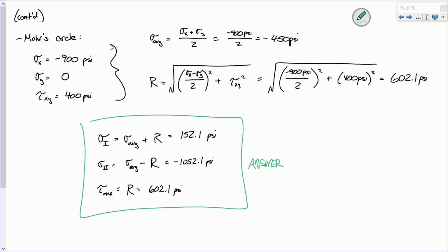By changing your orientation, the stresses get higher, okay? We're looking for worst case scenario as designers, okay? So while our bending stress formulas and shear stress formulas work nice to give us those individual stresses, when you've got multiple stresses going on, everything changes. This shear stress serves to up this at a different orientation. And vice versa. Here's our shear stress according to that orientation, but really the maximum shear stress is 600. You see what I mean?